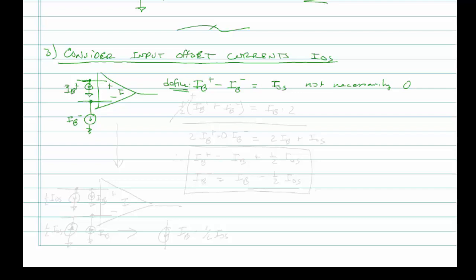And if I go back to the transistor drawing, the differential pair, on the previous page, what this comes down to is the fact that there are slight variations in the fabrication of those two transistors. It's either from the semiconductor doping, where even though the concentrations of the impurities may be quite close, because of the small geometry, there may be some localized differences in doping, or it might just be the precision, the uncertainty in the geometries of that device.